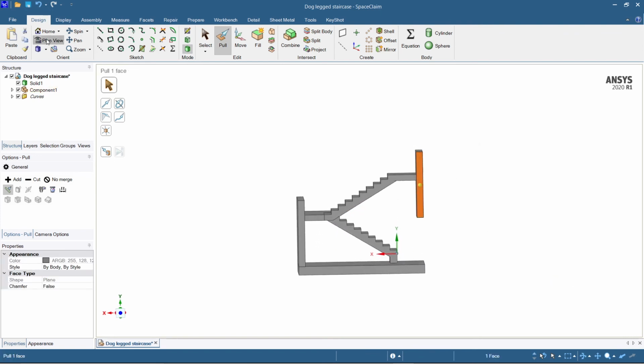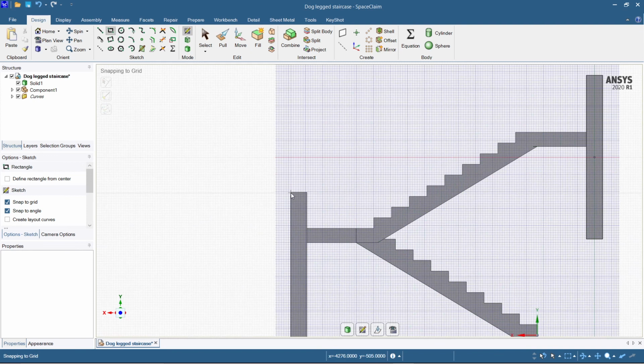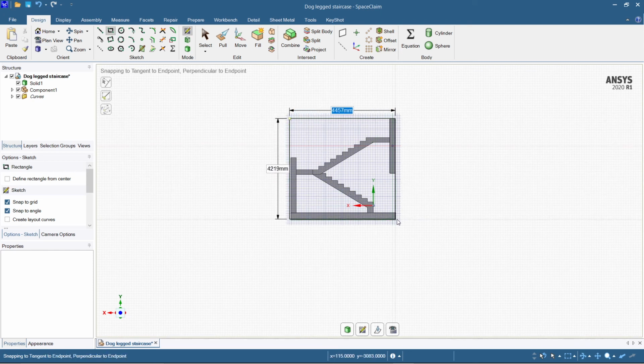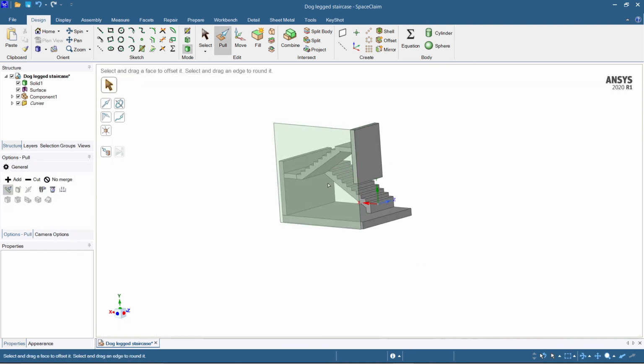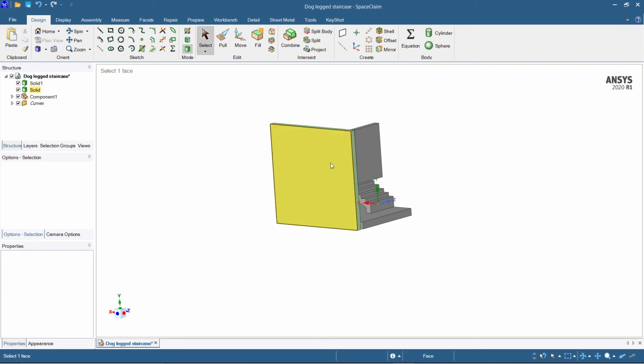So just plan view, again take a rectangle here. So what we'll do, we'll go up till here. Okay, we'll draw up till here. So we'll go with this edge. Mainly we'll go with this edge. Most probably we'll go with this edge here. Once again, let's go with this edge for time being. Okay, fine. So again rectangle here, and again this is so easy in this one. So wall will be always a 230 mm wall. We have taken 230 mm wall, so wall has been selected.